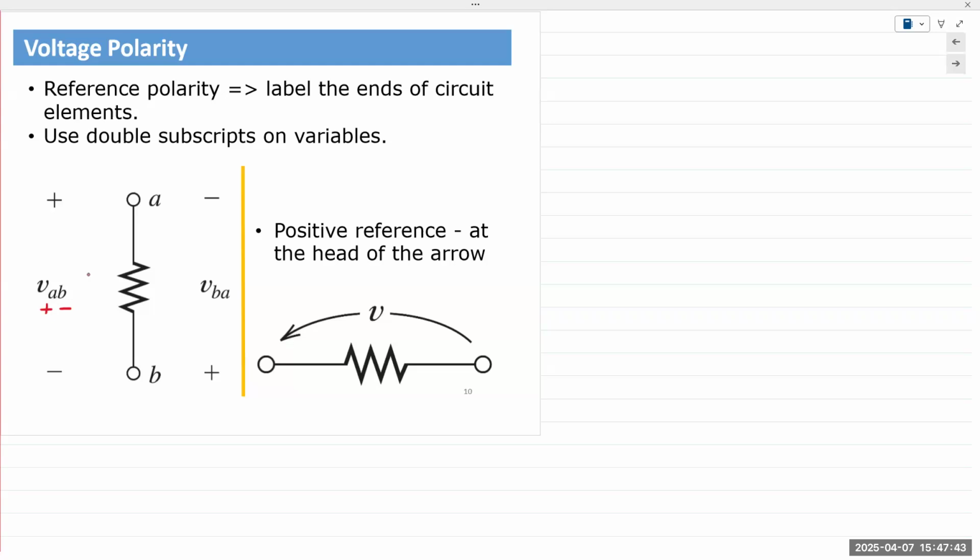Now, in the lab, have you all used a multimeter? Or will be about to use a multimeter, hopefully, right? So a multimeter has two terminals, right? One positive, one negative, marked as red and black. The black terminal is the most important because that's the common reference point for all measurements. No matter which multimeter you're using, that black terminal is the most important. It'll be labeled as COM, common. And that point gets connected to your reference point.